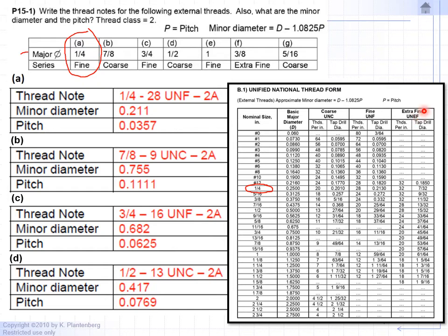One way to decrease the weight is to keep the bolts short, but then you have less thread engagement. So we go with extra fine, where the threads are a lot tighter. We need enough thread engagement for the bolt and the nut to do their job.